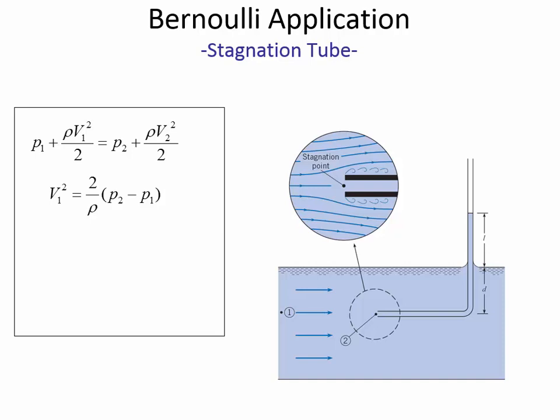We can say, let's solve for the velocity at 1. Even though we don't know what it is, it's somehow related to the change in pressures. How much the pressure changes at 2. It went through a change of pressure because all of the velocity head was converted into extra pressure. The energy can't be destroyed, so it just has to change form. So what this next step of the equation is saying is that the velocity at 1 was transformed into a pressure increase.